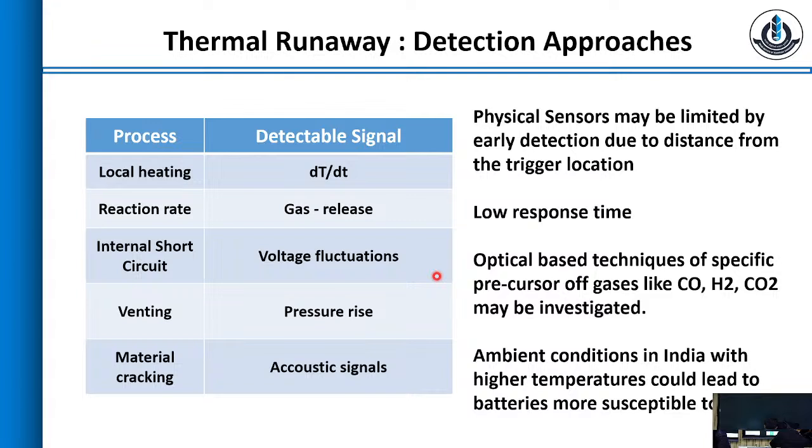For those, if you look at the current cycles being drawn or the internal resistance of those batteries, those things will give you an idea about the health of the battery. So typically during charging, what is the energy that it is able to contain? How much time is it taking to fully charge? What is the temperature of the battery?